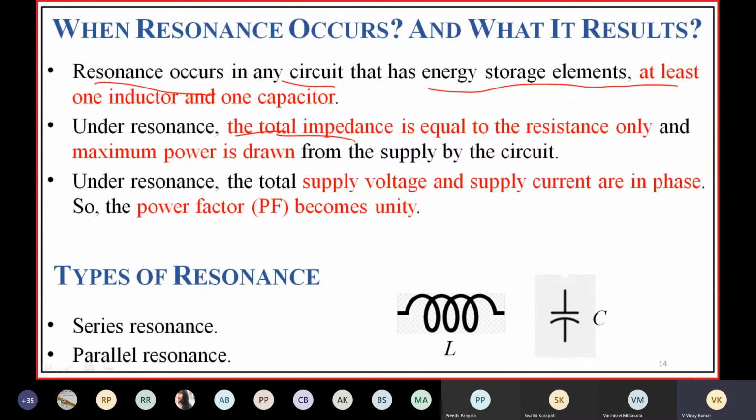You are making the imaginary part, the reactance, 0. So maximum power is drawn from the supply by the circuit.